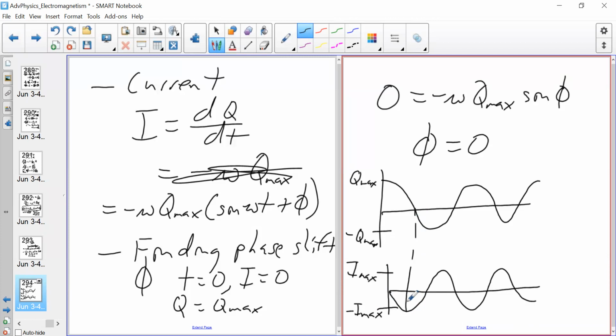And there is your mathematical, graphical picture of the oscillations between the charge in a capacitor in an LC circuit and the current through the inductor. So when one is min, the other is max. Boom, boom, boom, bam. And we can see that harmony between sines and cosines. When sine is maximum, cosine is min, and they're off by a phase shift of pi over 2, which pretty much dictates why one is going to be a max at some number, and the other one is going to be a min or 0.